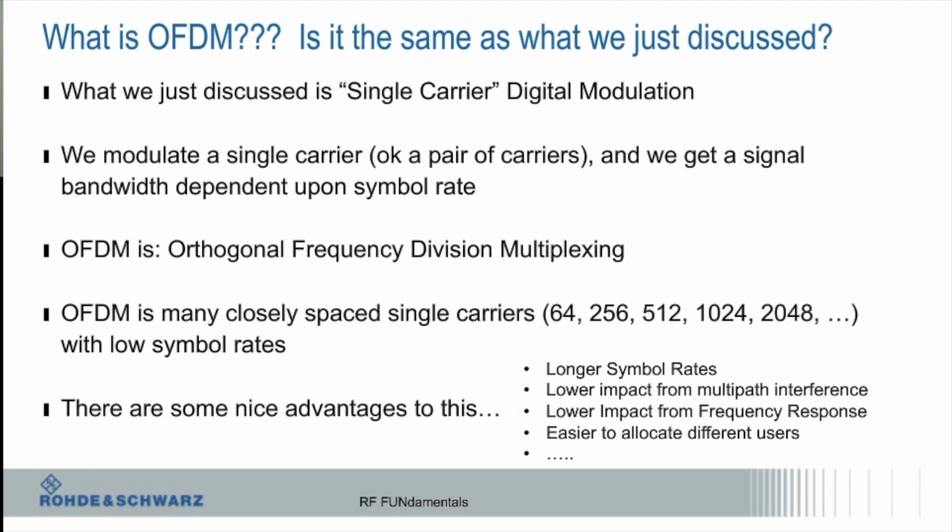It's going to look at the channel. So we talk about channel estimation, and we talked about a lot of these other characteristics. It's going to try to send a 256 QAM signal over this channel, and it's going to say, you know what, I can't receive it. So guess what? I'm going to try a slower one, right? So it's going to do some analysis of the channel and determine what's the best thing for that particular channel.